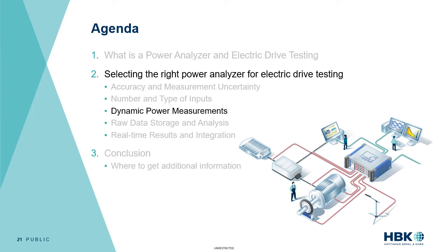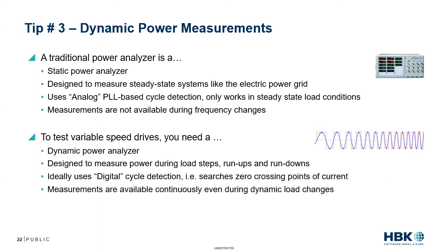Moving on to our next topic, it's dynamic power measurements, a very important factor when selecting the right power analyzer for electric drive testing. So a little bit of background on dynamic power measurements. First, a traditional power analyzer was originally created as a static power analyzer designed to measure steady state systems like an electric power grid, where the frequency really doesn't change all that much. It's around 60 hertz or 50 hertz.